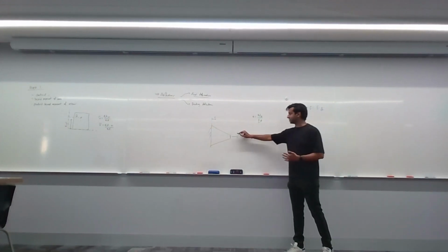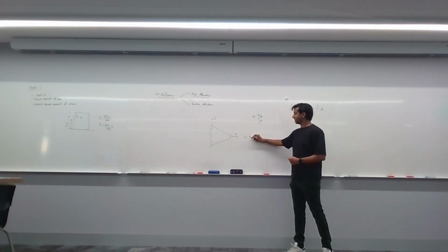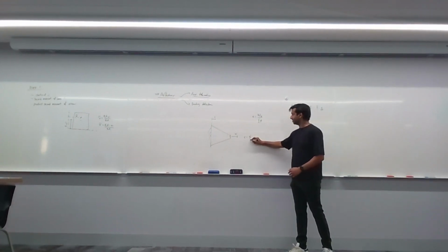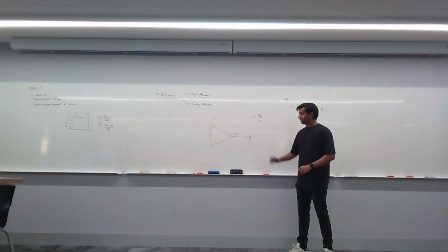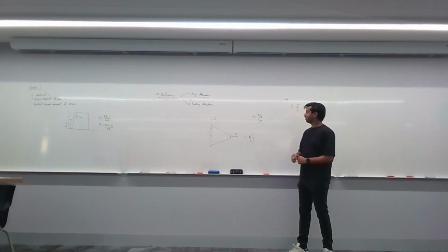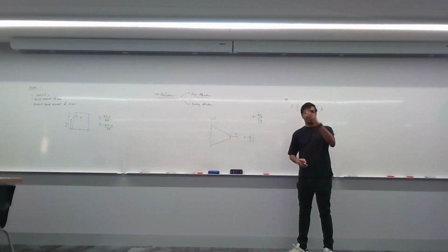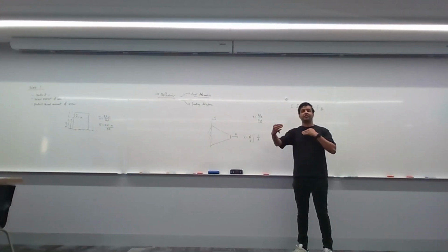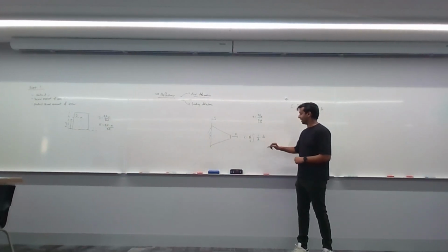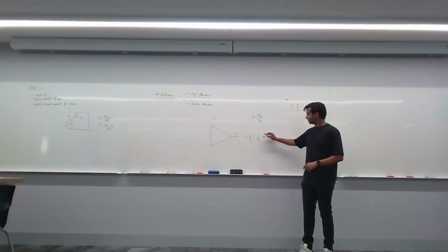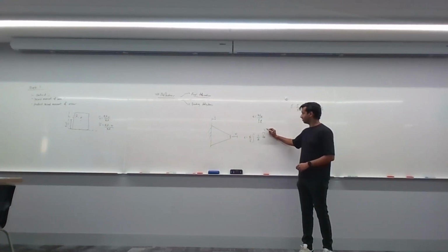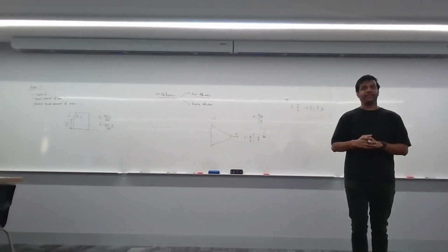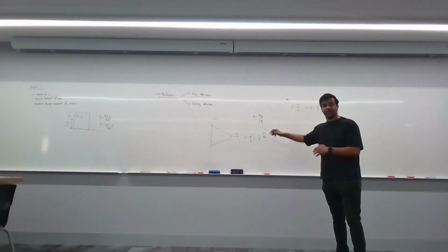In this case, let's say N is constant, so N's outside the integral. E is constant, so E is outside the integral. Then we chuck the integral sign on. A is what is changing. So A is changing, and you're integrating this with respect to length, which is x. So that's your L. It's the same formula, except you just have to remember that when you do the integration, this is how it's going to look like.